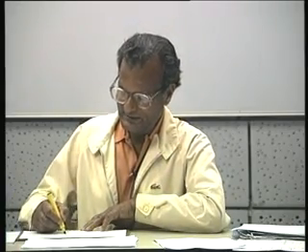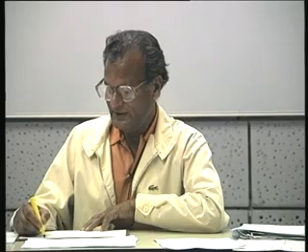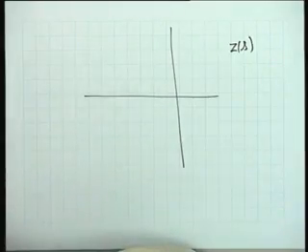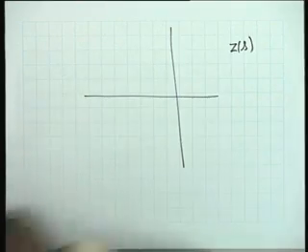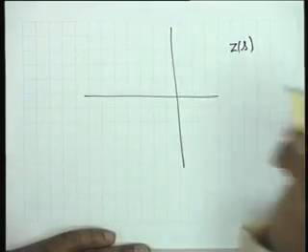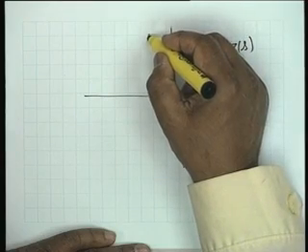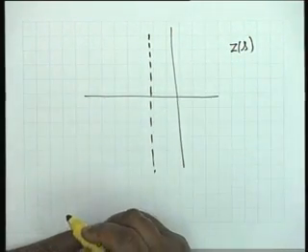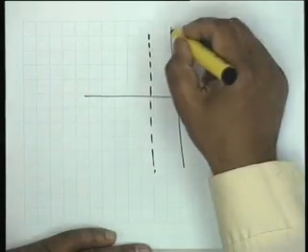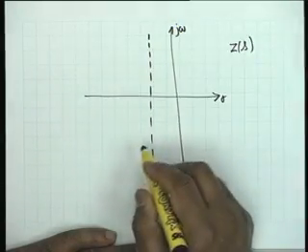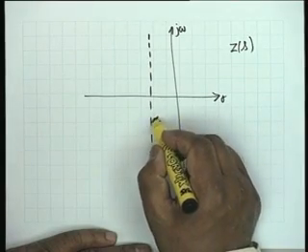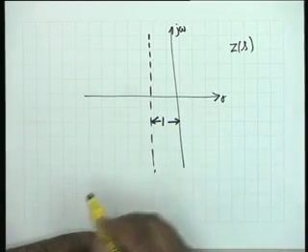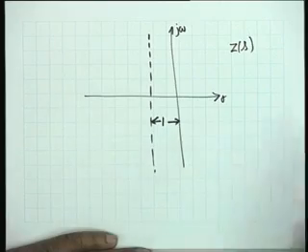I have been given a driving point impedance function which has not been specified to be LC, RC or RL, but its poles and zeros are given, and all of them are located on a line parallel to the j omega axis, at a distance of 1 from here, all right.